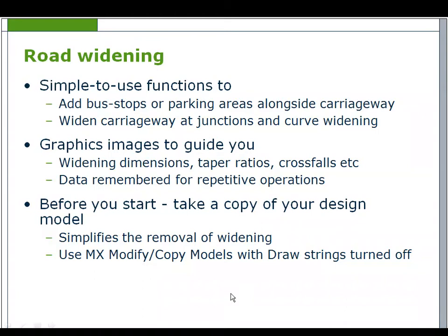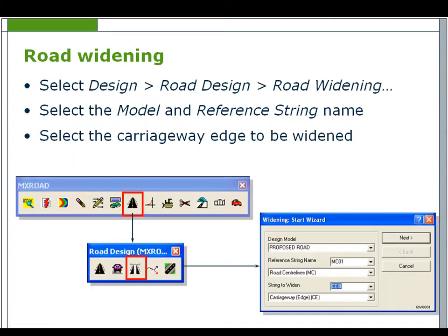The road widening wizard simplifies the design of bus stops or parking areas alongside carriageways. It can be used to widen carriageway edges at junctions and curve widening. Graphic images guide the user through widening dimensions, taper ratios and crossfalls. Data is remembered for repetitive operations.